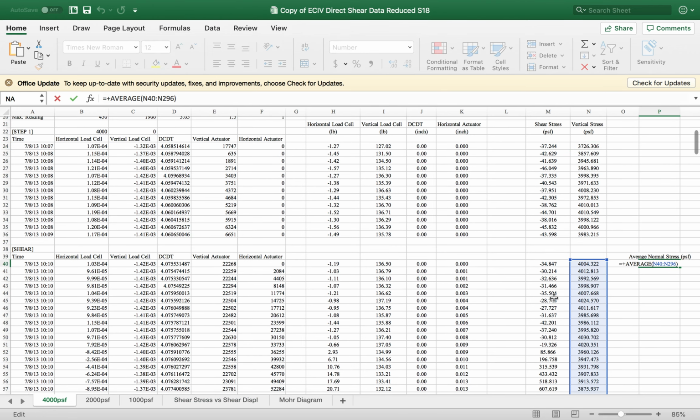And then using this data, if you right click again on the data, you have to be sure you click right on the dot, not on the trend line. There we go. Then you can add another trend line and say set intercept to 0, forecast backwards about 1,000, and be sure to change the color of it, make it something different than the black line.